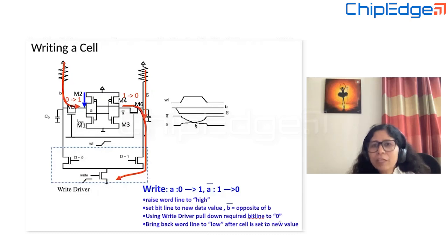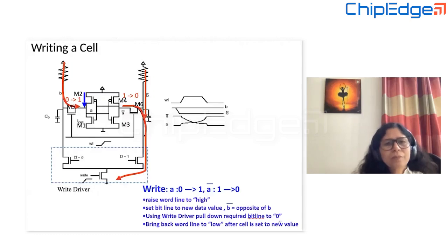If I have this kind of example waveform which I have shown, here the margin is good. Your internal node is flipping, and after some considerable time the word line is going off. So this is a good write margin when it comes to time-wise write margin. But the literal definition of write margin has more to do with how much bit line voltage needs to go down to make the write happen. In practical terms, within the teams, we start talking about write margin in terms of timing in this way. I hope I was able to clarify.